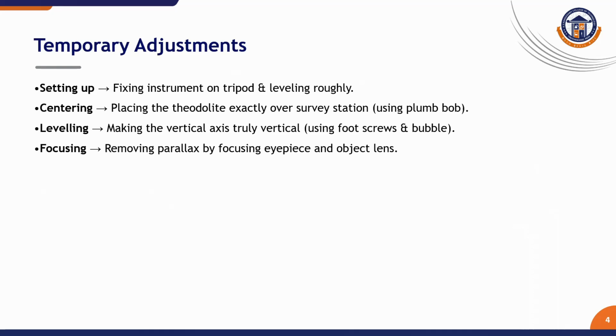One of the most powerful applications of the theodolite is to determine height and distance indirectly by measuring vertical angles and a known baseline distance. We can use trigonometrical principles, a process known as trigonometrical leveling, to calculate the height of inaccessible objects like towers, chimneys, or mountain peaks, which is invaluable in engineering projects.